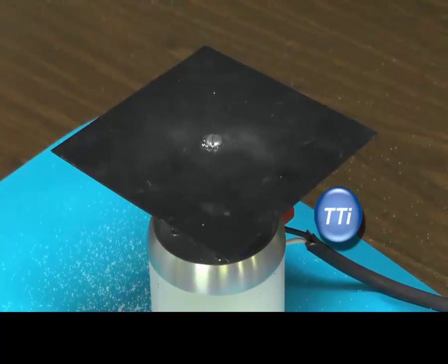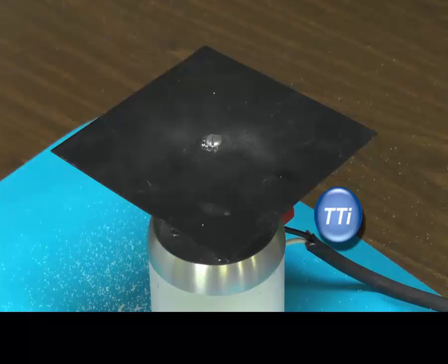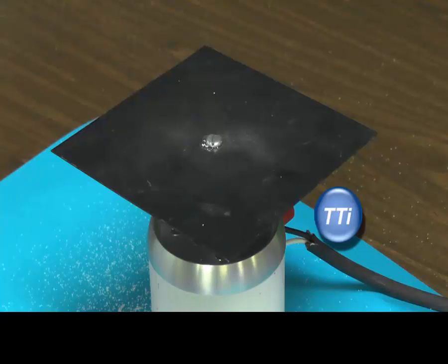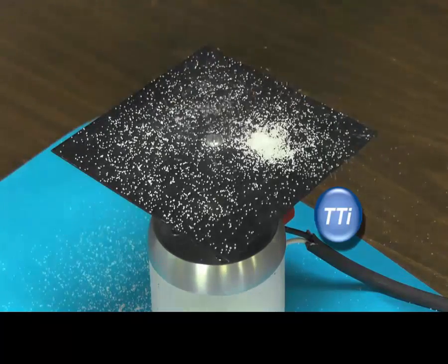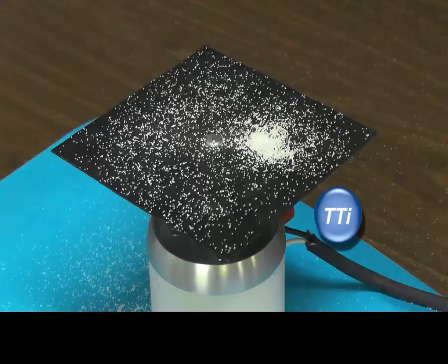We saw on the last beam mode that we were starting to get node lines that were not straight across the beam, but starting to move along the length of the beam. That's because the beam was starting to act more like a plate. So what we're shaking now is a small square plate. I'm driving it right now at 62 Hertz. I put the salt on, and I turn the power onto the shaker.